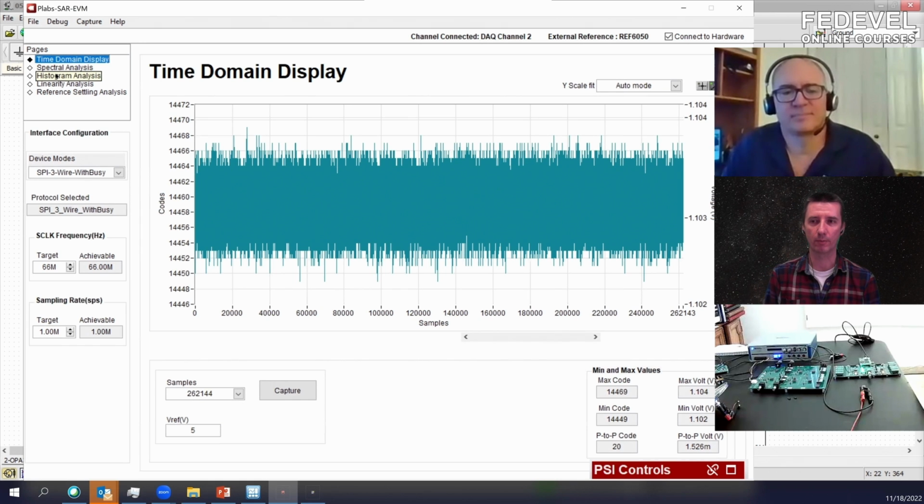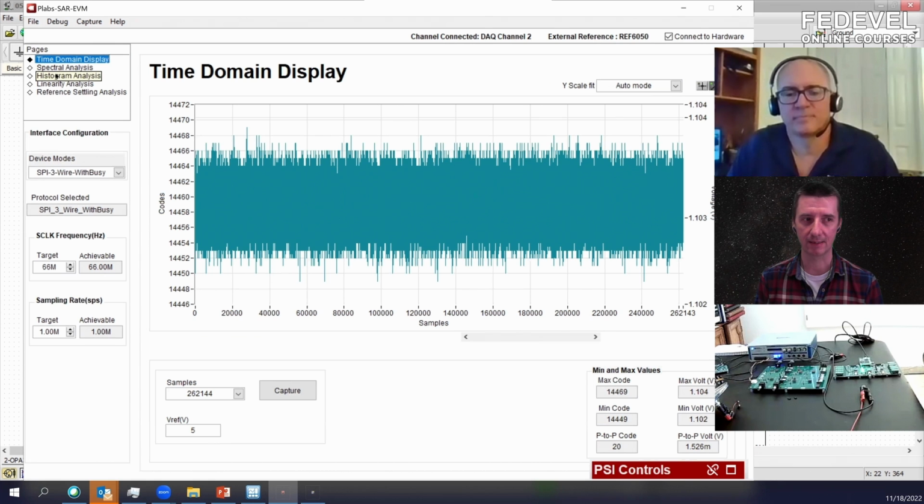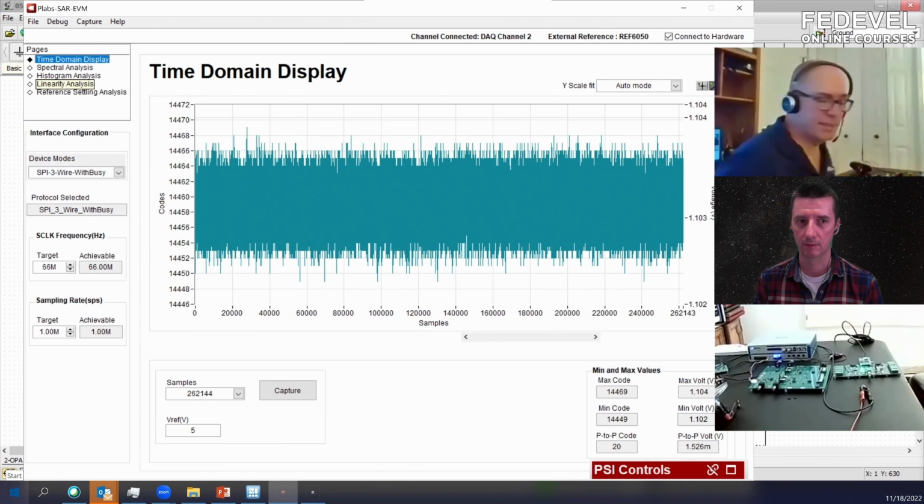That's interesting. So basically, you can get noise even from devices working at higher frequencies than what you are actually processing, or than the capabilities of your device. Yes. Now I can show another demo where we connect longer leads to this, and we can see 60 hertz pickup. Should I do that? Okay. Yeah.